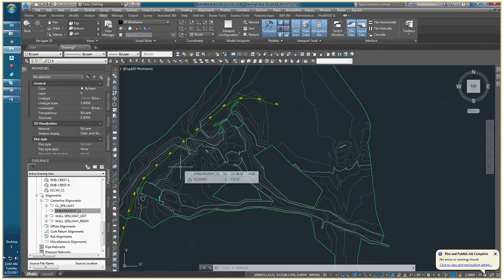So for dam engineering, we almost always show our drawings with flow, water, going up the page. In other words, the reservoir would be at the bottom of the page, and the dam would be in the center, and the downstream tailwater would be at the top of the page. Or sometimes from left to right, and especially when we're showing profile views and section views, we want to be sure that flow is from the left of the page to the right of the page. This is an industry standard, and is thus the Schnabel standard when we're talking about dam engineering.